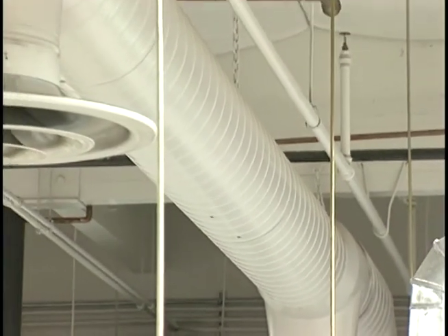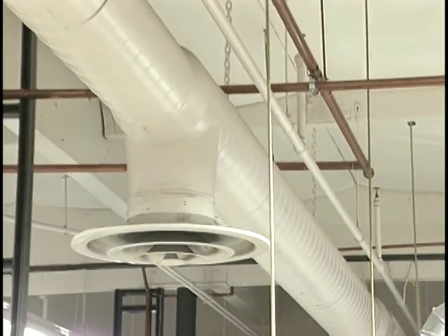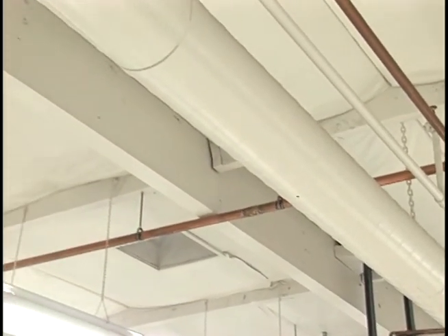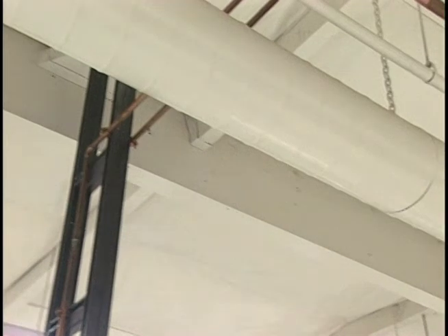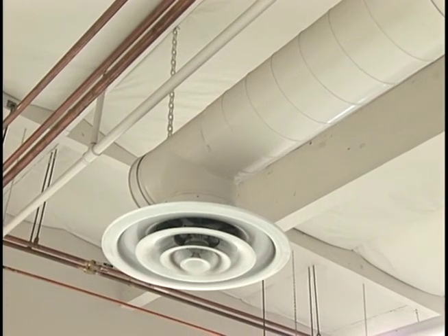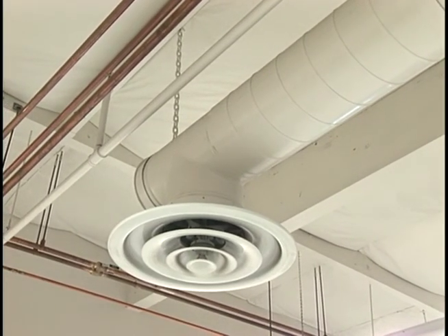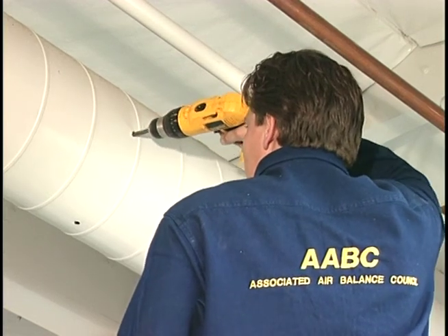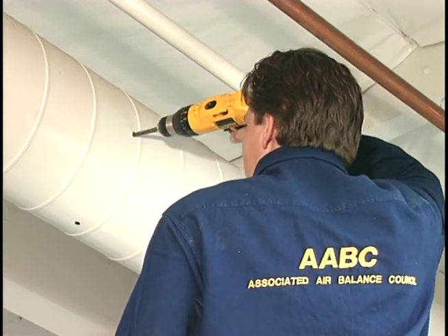The technician is going to take a pitot tube traverse in this branch just after the branch damper. 2 test holes will be drilled in this 10-inch diameter duct. Remember, in rectangular ducts, a number of holes are drilled based on the size of the duct. But in round ducts, only 2 test holes are needed. However, they must be located 90 degrees apart.